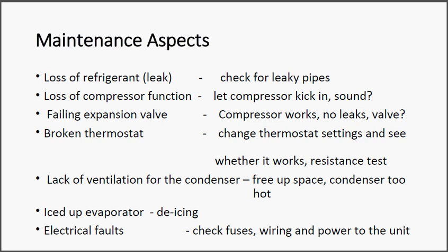It's a workaround, a temporary workaround, because it's going to happen very quickly again, is to possibly look at the contacts and to clean up the contacts of the thermostat. Yeah, it's most likely some bimetallic contacts in there, a bimetallic strip, and just clean them up. Get some cleaning chemicals, and obviously with all the health and safety, try and clean them up if you can, and then fit everything together, as you should do it, and then put it back in.